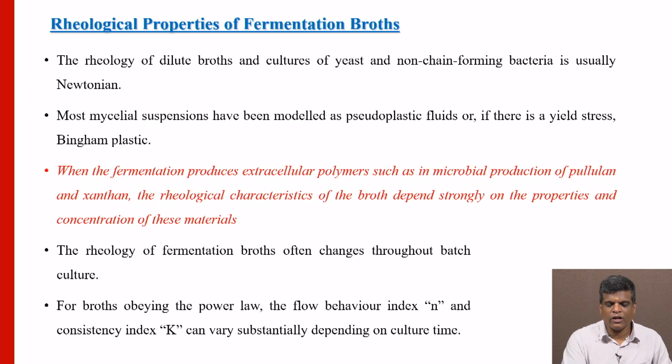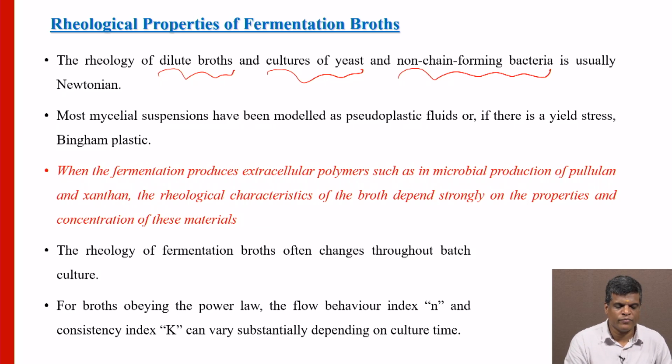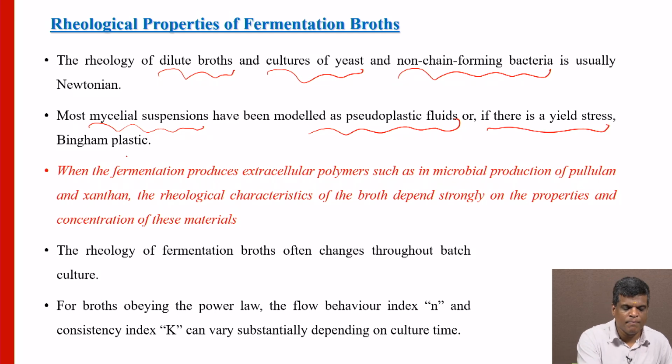Usually Newtonian here: the rheology of dilute broth, cultures of yeast, and non-chain-forming bacteria always come under Newtonian. Most mycelial suspensions are pseudoplastic. If there is a yield stress, then it will come as a Bingham plastic.